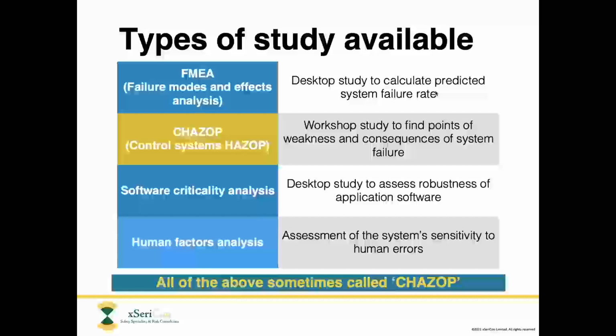And we can identify the different ways in which it can fail and calculate a failure rate for each of those. And the FMEA can also give us very useful data, for example, relating to the effectiveness of different testing methods that we can do. And will also tell us things about what kinds of critical spares we may want to keep in stock.